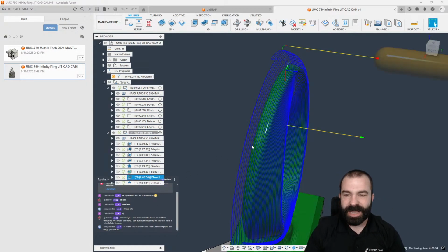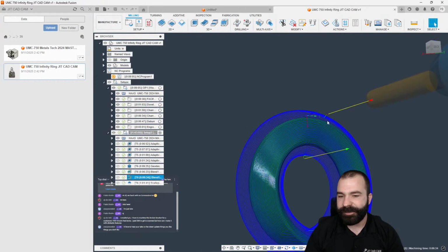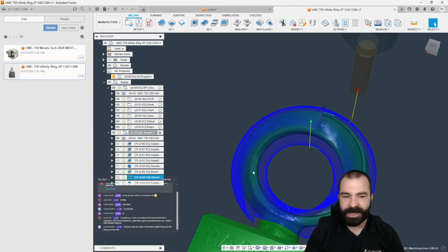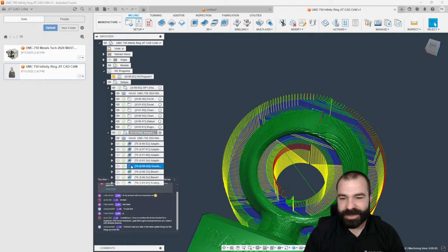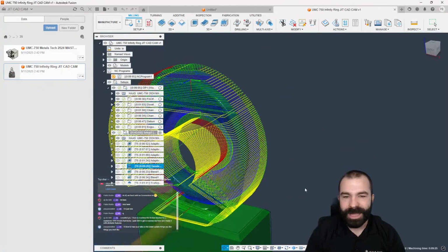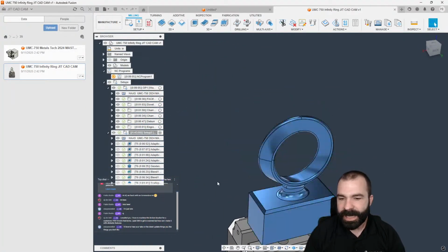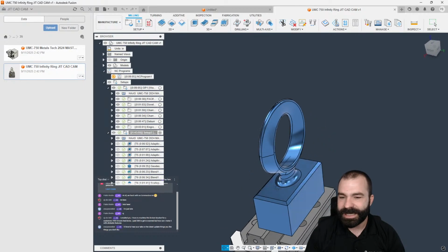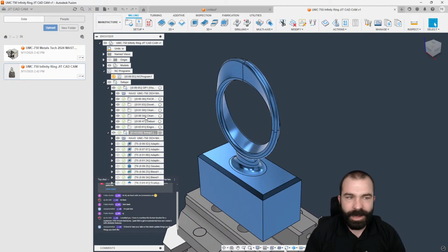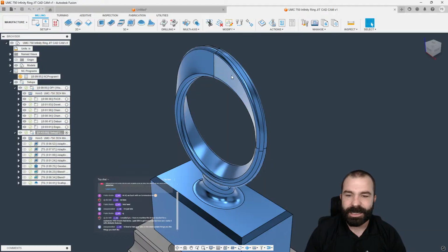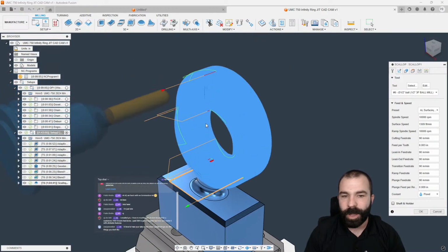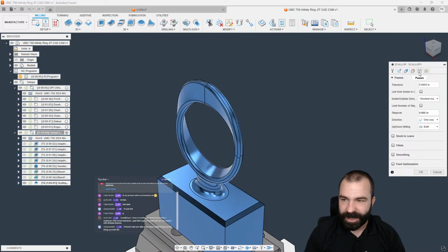So the question at hand was asking about getting a very good surface finish on a part like this. And as you can see, they've gone through and created quite a lot of toolpaths trying to achieve that task, right? Now, I don't know the necessary use case of what they're building here, but I would say at the end of the day it's going to come down to what the surface finish needs to be. Again, there's a lot of factors, but I do want to start off by looking at a couple of use cases. Like one, the use of the actual scallop toolpath.